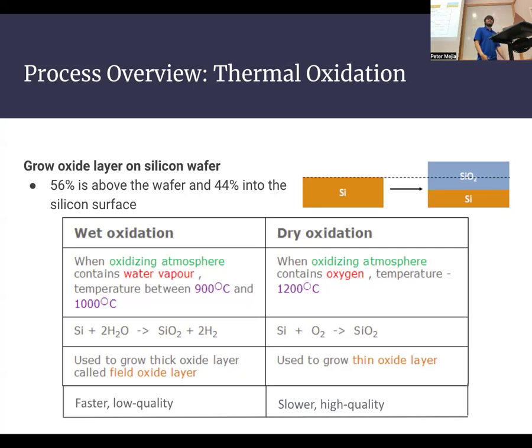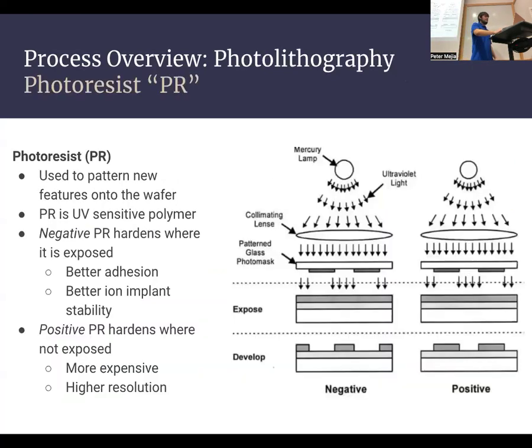We have charts for each of those processes. They have equations and charts, so you can pick some anticipated thickness. We have a chart for a bunch of the steps for the processing. You kind of fill in certain areas, but it's generally planned out so you're not growing oxide after you etch or something weird like that. So that's generally thermal oxidation.